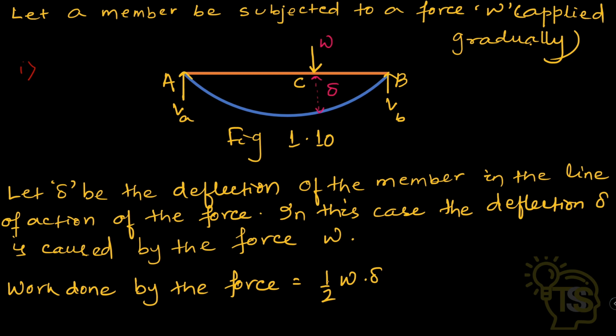We have taken W and del because here the deflection occurs at the line of action of load W. That's why the work done by the force is equal to half W into del. And let's see case 2.